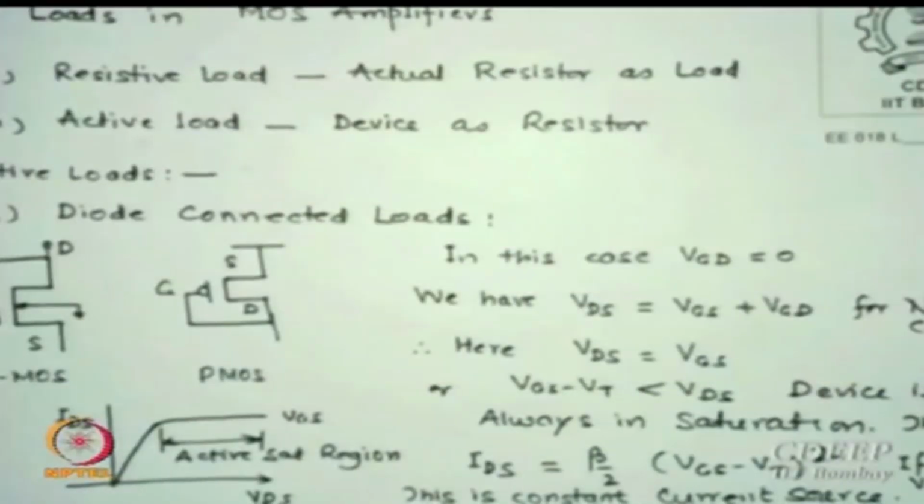So we said the load resistance of typically 10 to 40k will be required, and for those values the aspect ratio is so high that it will be very difficult to put more than a few resistors on chip. That means it will take more area for the resistor than the transistors. So we said okay, we will not like to use resistors made out of normal semiconductor. Please do not think that I will never use it, I will have to use it somewhere, but normally I will avoid it.